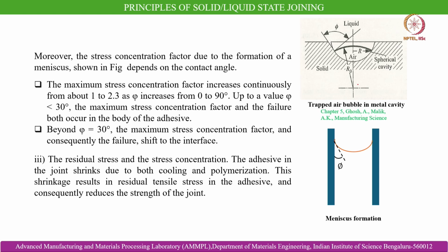Moreover, there is the stress concentration factor due to the formation of a meniscus. As we have talked about the entrapment of a bubble, that will also form a meniscus within the adhesive body. The maximum stress concentration factor increases continuously from about 1 to 2.3 as phi increases from 0 to 90 degrees.